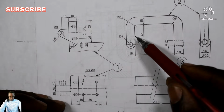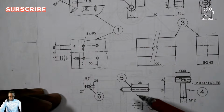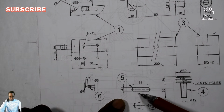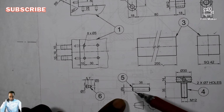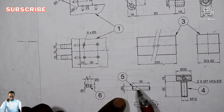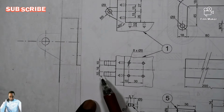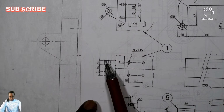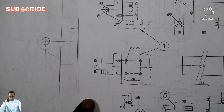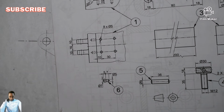So if this is diameter 9, it does correspond with what? With that one, and it's going to be held together with what? With item 5. So item 5, the length of it, if you say 36, the length of item 5 must correspond with this one. So this 36 corresponds with what? With this, because from here till here is 36, because 10 plus 10 is 20, plus 10 is 30, plus 6 is 36, which corresponds with what? With the length of item 5.